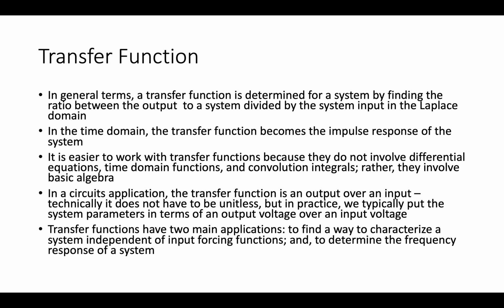In general terms, the transfer function is determined for a system by finding the ratio between the output of a system divided by the system input in the Laplace domain. So in the time domain, the transfer function would be the impulse response. In other words, the defined response of a circuit to an impulse input. It's a lot easier to work with transfer functions than it is impulse responses for several reasons. First, they don't involve differential equations or time domain functions, and specifically they don't involve convolution integrals. Rather, they just involve basic algebra.